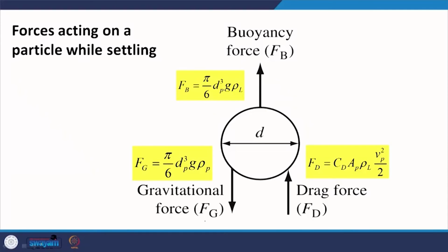So we have a particular velocity of settling, and we have the depth of our settling tank, and our particle should cover this vertical distance. Based on which aspect will it be governed? It will be governed by the settling velocity. Settling velocity, how is it coming into the picture? Well, gravity is always our friend.